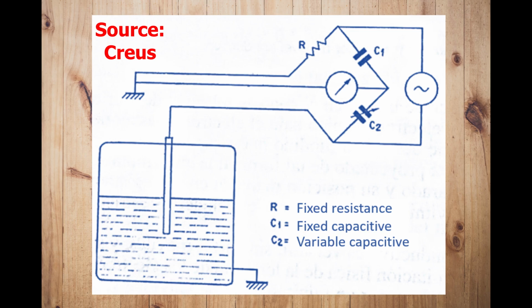However, in conductive liquids, conductive solids or liquids that are in suspension or emulsion and exist in air or vapor bubbles decrease and increase the dielectric constant of the fluid, which leads to an error. Furthermore, by lowering the level, the insulating portion of the electrode can become covered with a liquid, and the additional capacity this represents also leads to considerable error. The accuracy of the capacitance transducers is plus minus 0.1%.